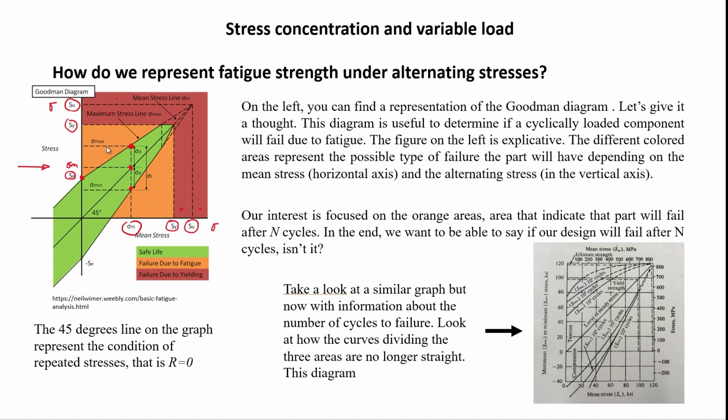But if you find yourself in the orange section here, then you need to take care of fatigue, and you need to answer the question of how long it's going to last, how many cycles. Remember, with fatigue you also answer whether this is going to last 3 years, 10 years, 20 years, 30 years, something like that.